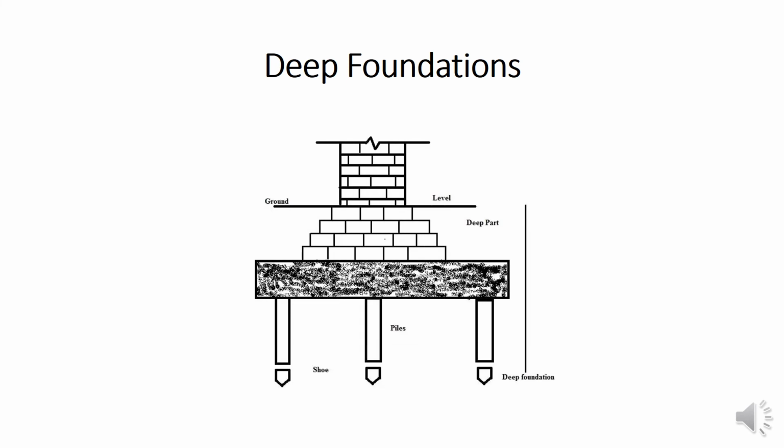Next is a deep foundation or deep footing. Shallow foundations are used in case of small buildings or structures which carry lesser load, and hence the loads are dissipated to the soil mass at a much lower depth. However, when we are considering a large structure carrying heavy loads, the loads are dissipated at a greater depth where usually the soil bearing capacity is quite high. One guideline of difference between shallow and deep foundation is that in case of deep footing, the depth of foundation is more than the dimension of the structure. Usually the width is considered as the dimension.